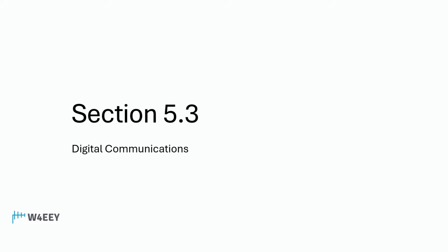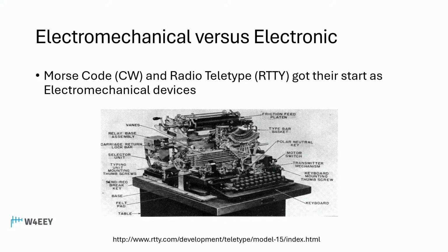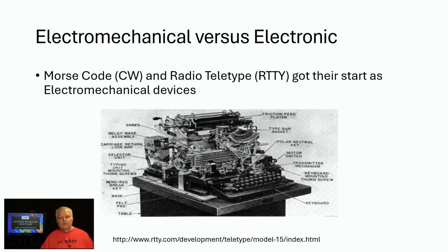And we looked at packet radio as an early form of digital communications in amateur radio. But even before that was teletype. Teletype got started as a land-based system where you could send text information via landlines, and then radio operators determined how they could use it over the radio frequencies. And we looked at mark and space tones, the frequency shift keying. That's what they came up with.